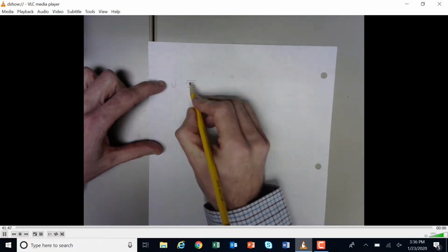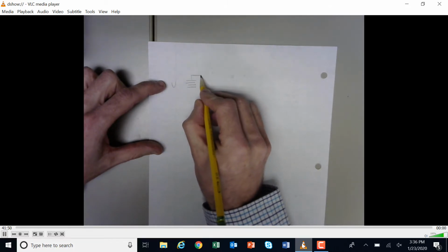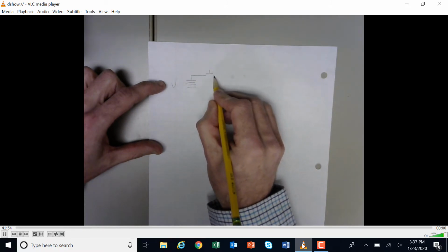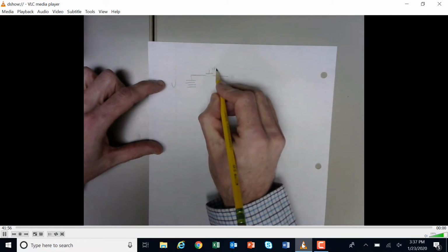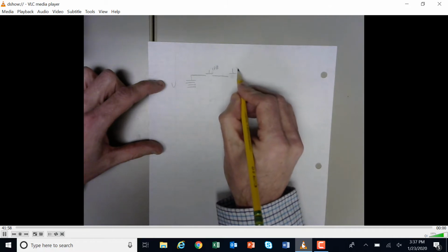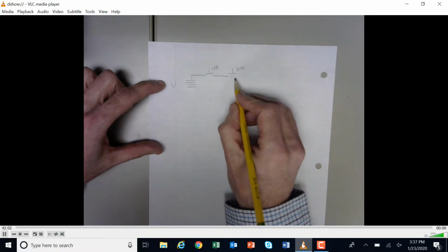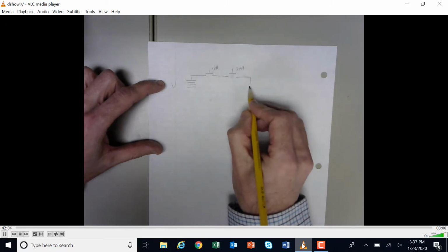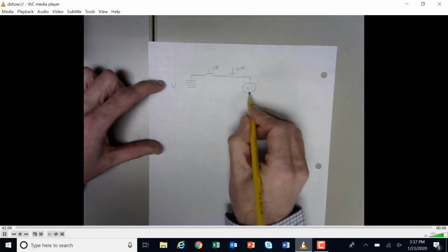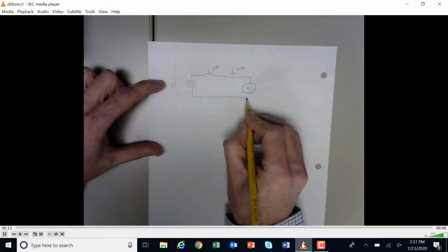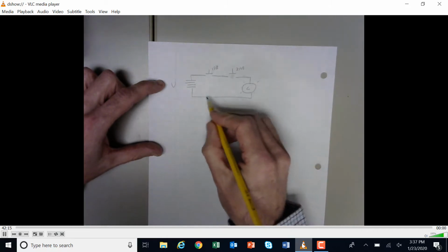or DC voltage source. And it would be going to, in this case we were using a push button, so let's use this symbol for a push button. We'll call this 1 PB, and let's call this 2 PB. Okay, and then they are momentary, and they're going to turn on an indicator light. So let's do a light right here, or 1 PL, one pilot light, and then we could close the circuit up here. Now remember, this is the basic circuit.